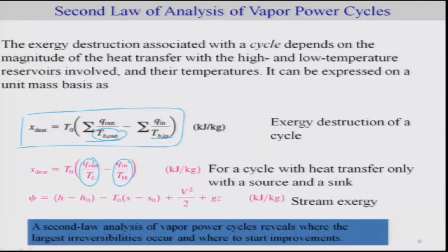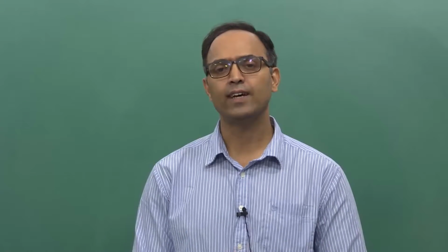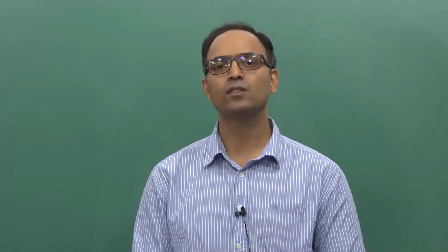Okay, so assuming this is a sink and this is your source, and this is, of course, the exergy which we can make use of. Now one can analyze such a problem, but the idea behind using the second law is to find out the largest irreversibility, and that's where we can also find out how to improve our process for the problem at hand. By finding the highest irreversibility, you can possibly come up with a new design which can minimize such irreversibility.